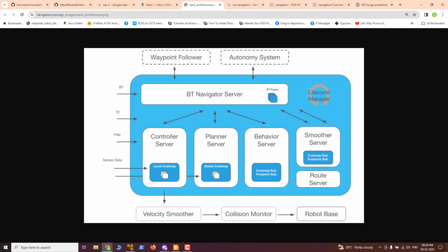So it's doing many things, and we are just sequencing the operation. That is the main change that happened in ROS 2. It's called the behavior tree, and there is a behavior server which handles it. We can sequence the behavior tree using a C++ or Python program, so you can programmatically control the sequence.